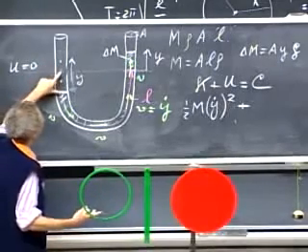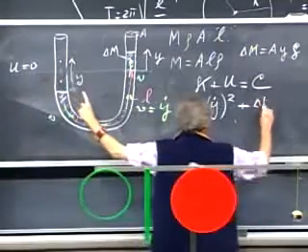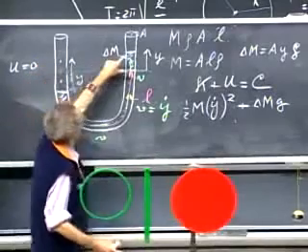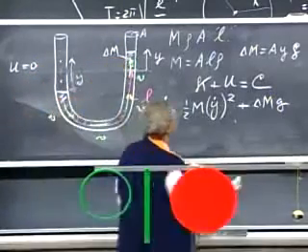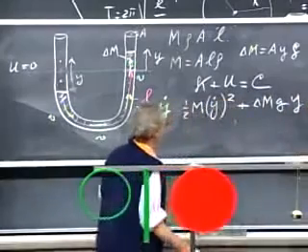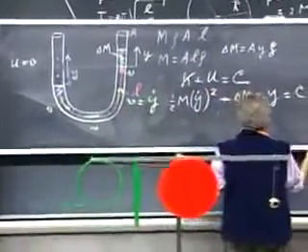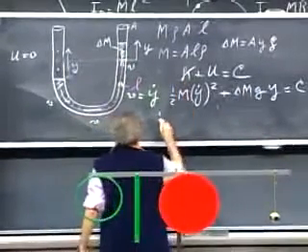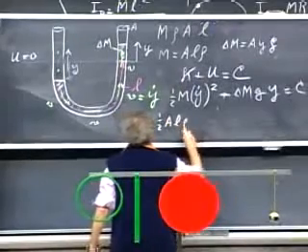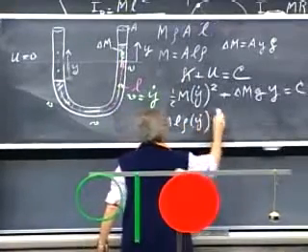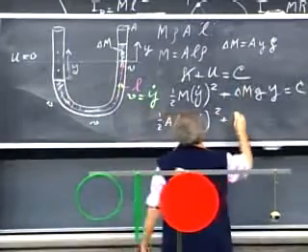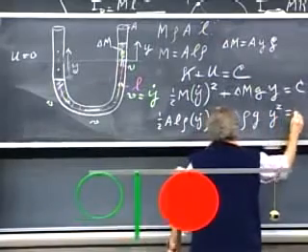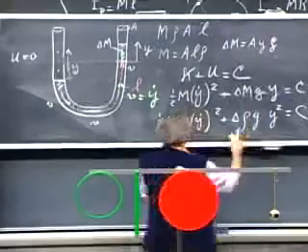And so I move an amount of mass, which is delta m. I move it over a distance y. I bring it here, but that makes no difference, of course. And so this is the total energy, and this is now a constant. So I'm going to substitute in there the A, L, and rho, so I get 1/2 A L rho velocity squared plus A rho g times y squared equals a constant, because I have a y here and I have a y there.